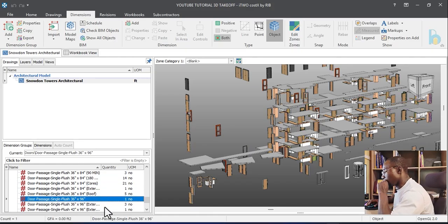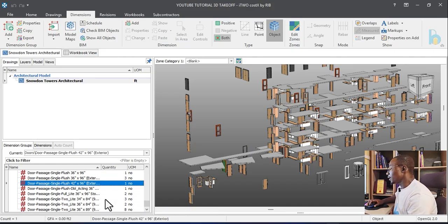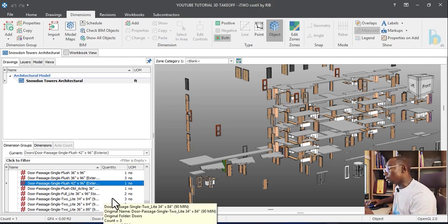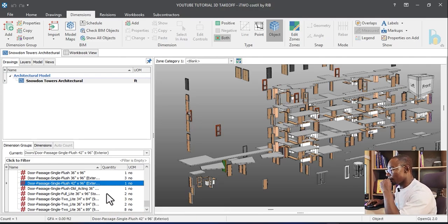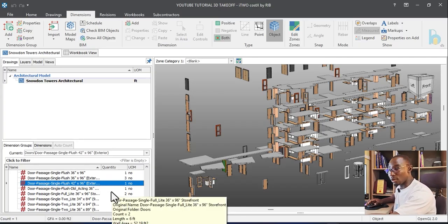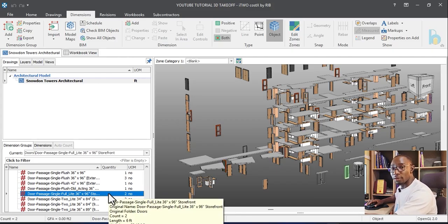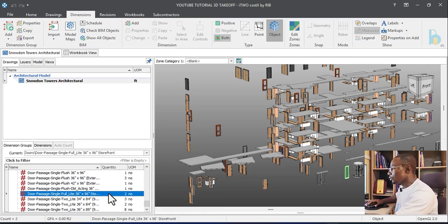But one thing with CostX, you can see here, when we use the BIM imports using the second level model tree, we have our exterior, interior, and all other doors. And we have our ceiling finishing and everything for the exterior and interior, everything in one folder. So CostX has this function that you can use to filter how you want the template to import your data.